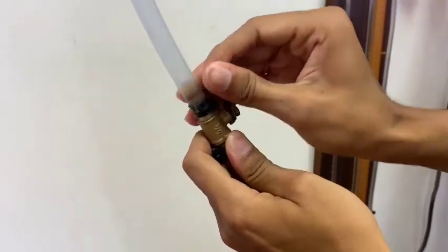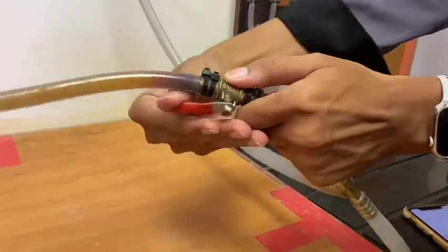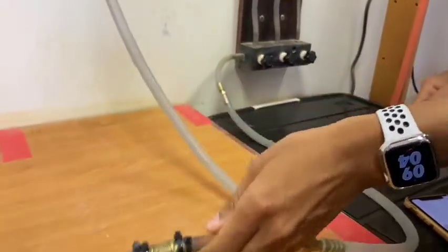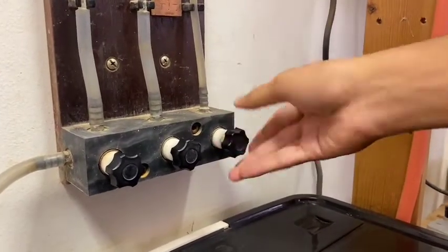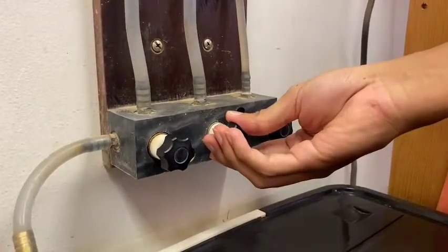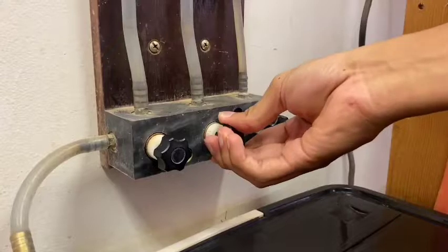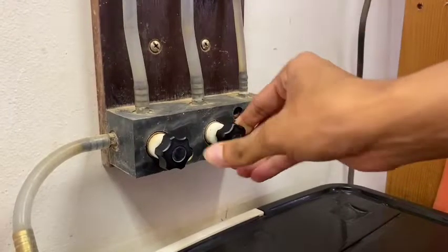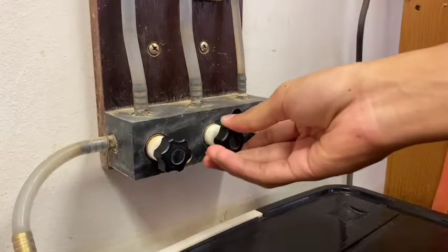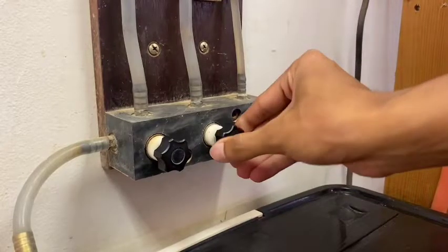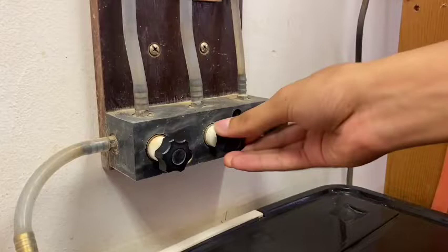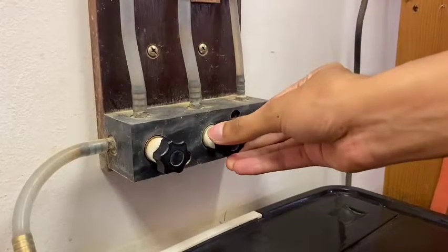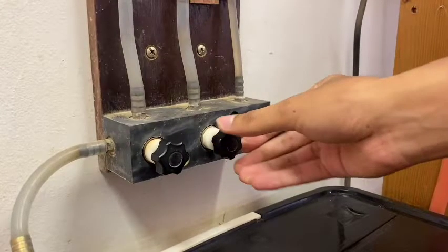So first we need to open the valve and fill the water into the standpipe to a marked initial height of the standpipe, and we record the initial reading for height H1 and time T1 before the commencement of the test. And then we close the valve and start the test by observing the flow of water and the time of the reduction. Once the water reaches the final height mark, stop the time and record the final reading for height H2 and time T2 simultaneously.